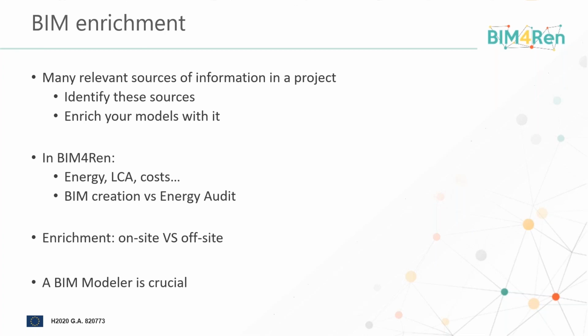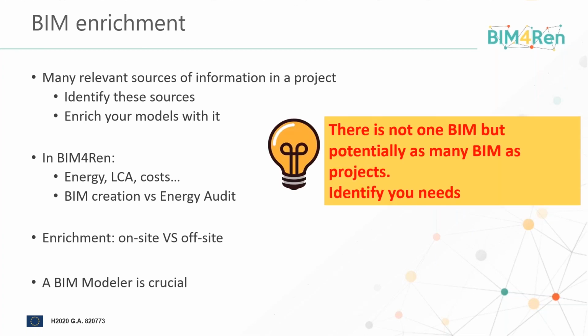Again, another key message. I think there's not one BIM, but potentially as many BIMs as projects, and every time you want to have a BIM project, just start by identifying your needs. The needs is what will you use this BIM model for? That will help you to identify the data that you need and the tools that you need to assist you.